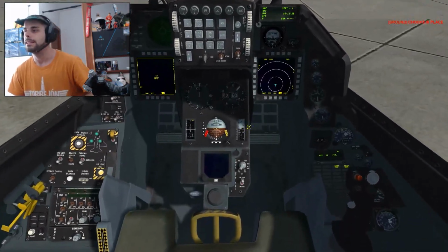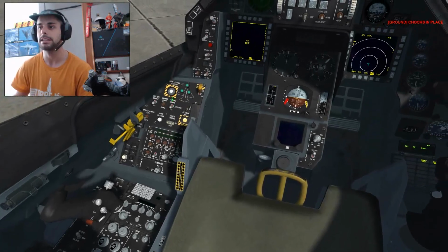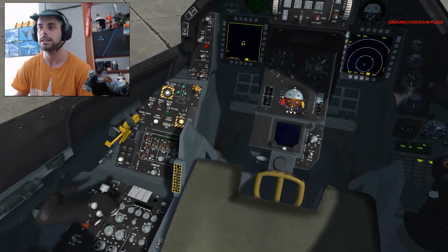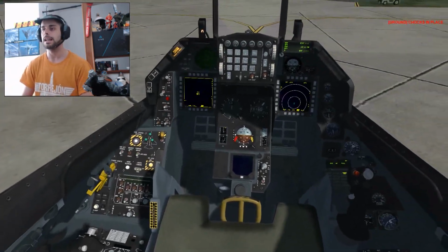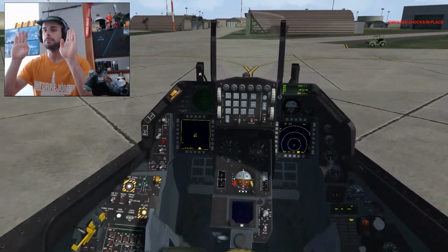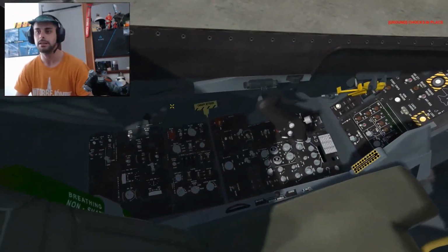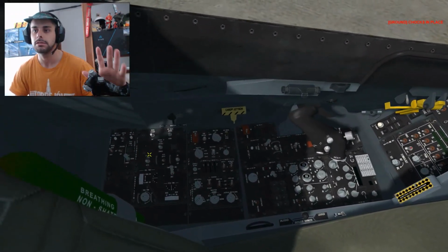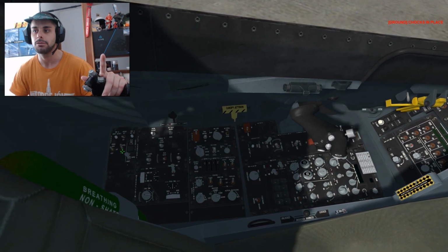Okay, let's continue performing this test, and never use the parking brake in this test. Okay, parking brake must be off there. Down position off. Okay, and also you must back up the chocks with your pedals braking, and now I'm going to hold the left click.